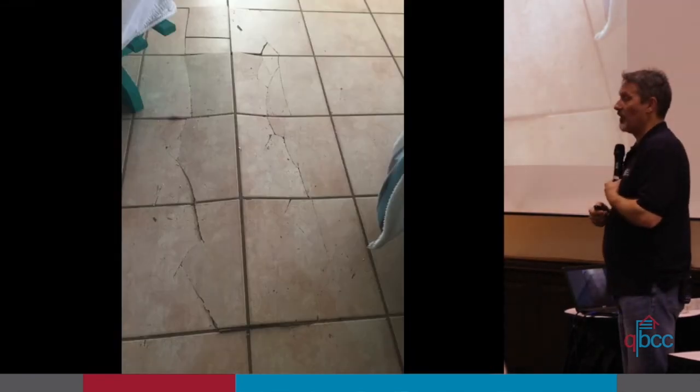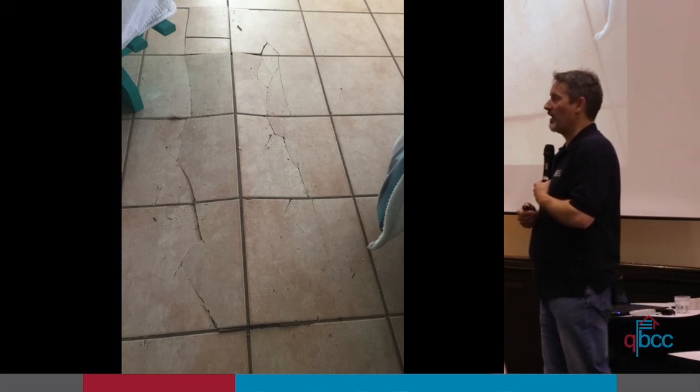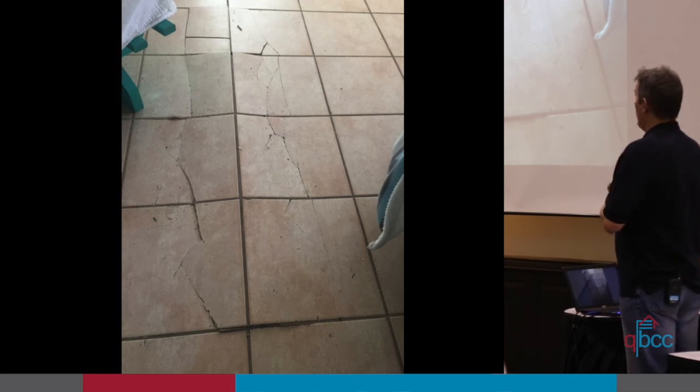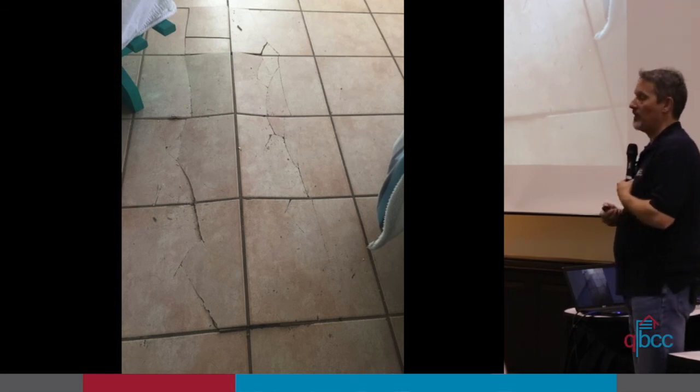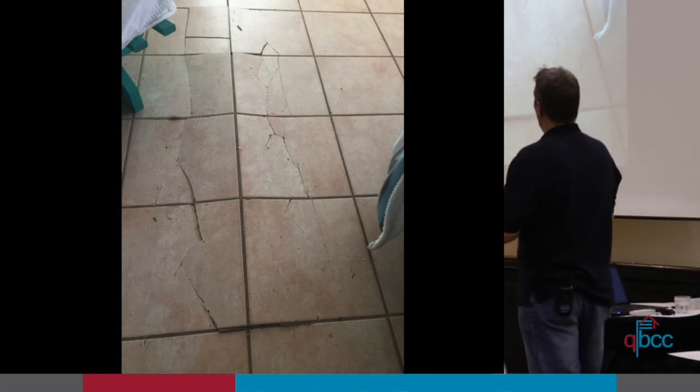So here's an example of some stresses on some tiles, and the waterproofing underneath that has no chance. All right. And I'll tell you what happened here. Basically they stuck tiles onto a five-day-old concrete slab. Concrete still shrinks as it cures, tiles not so much. You get that whole blow up in the middle.